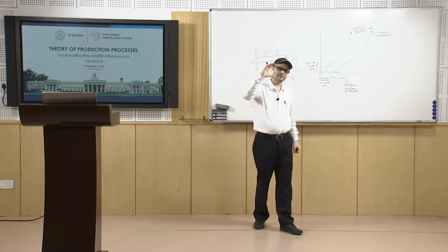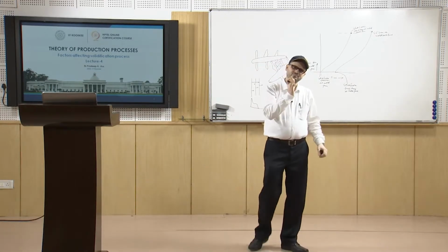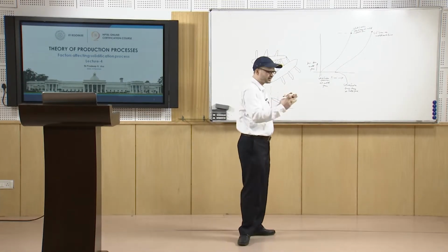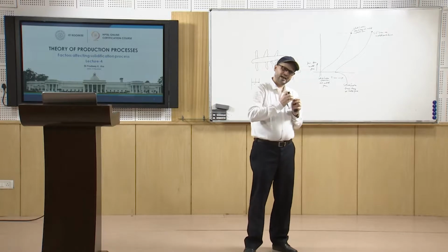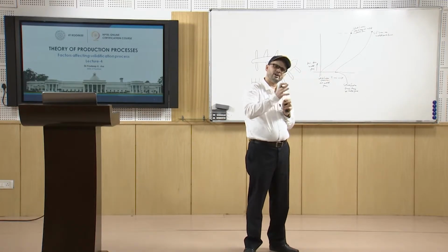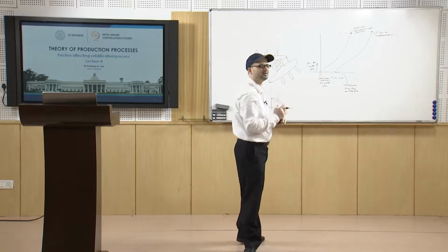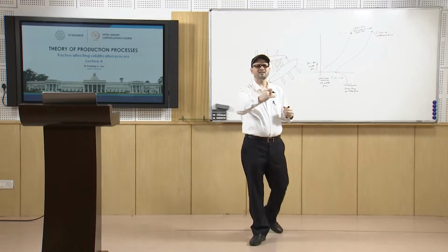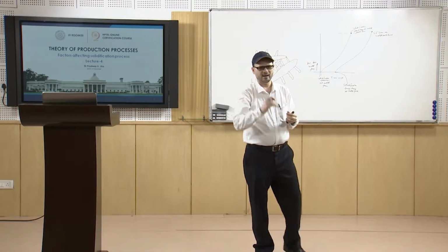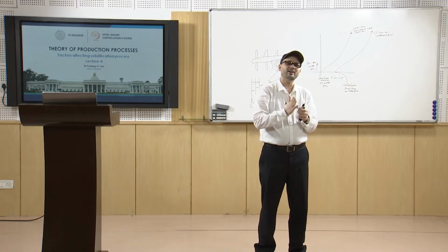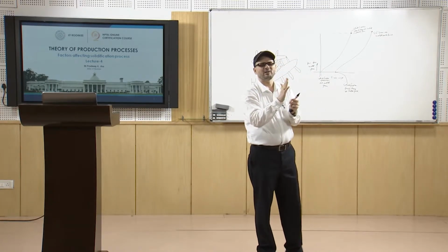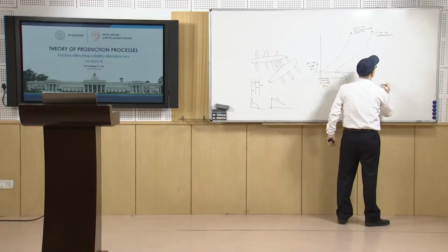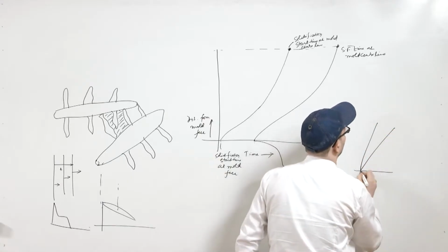Now, in the middle portion, the temperature differential becomes low because of the release of latent heat, and that latent heat goes towards the central portion. So that differential will be even lower and lower. That will be equalizing the temperature, and your heat extraction rate or the thermal gradient line becomes smaller and smaller. So earlier the gradient line was like this, it can go like this and this.